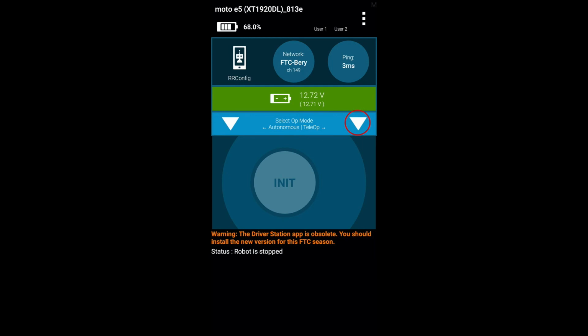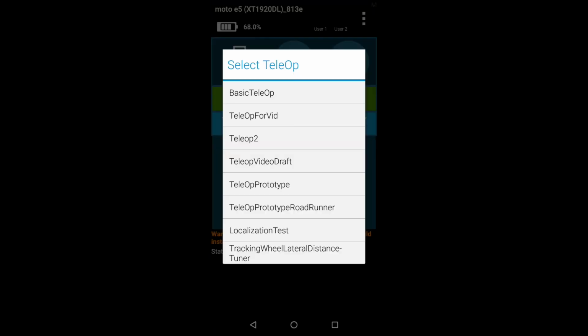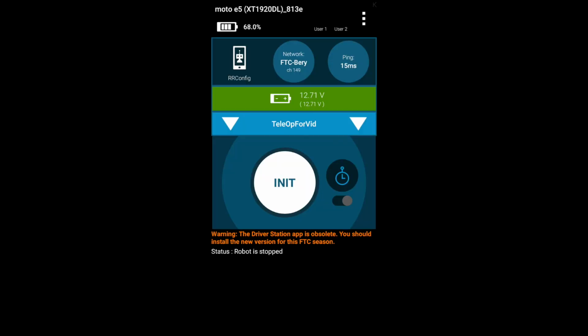Now it's time to run the TeleOp program. Select the TeleOp dropdown from the top of your screen and select the program you just wrote. Plug in a USB controller and initialize it by pressing the Option button and the X button. Initialize the code, then run it. At this point, you should be able to drive.